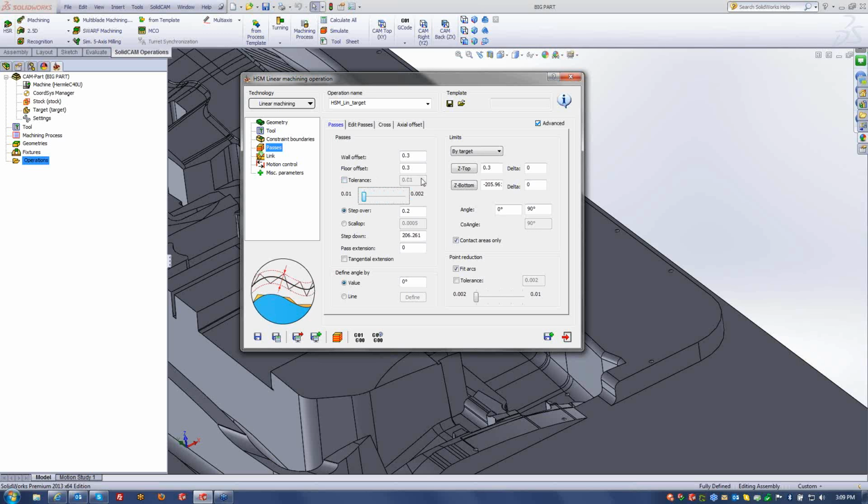We have this problem with new customer. Nobody will know, okay, I want to do part, but which tolerance I want to use? A lot of question here. SolidCAM add slider like the eye machining. Okay, here I can work between 0.1, okay, and you can move, and you can see each step, we work with different tolerance. Of course, I can handle all this tolerance from the SolidCAM settings, and I want to show later.